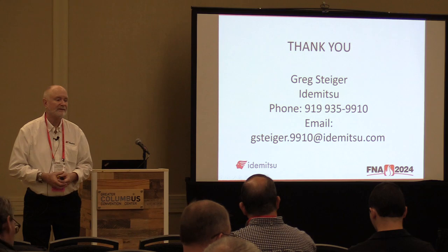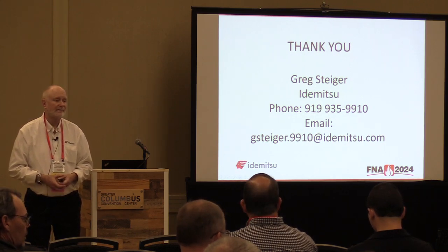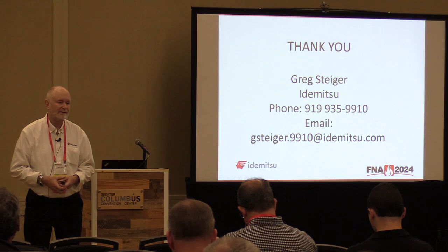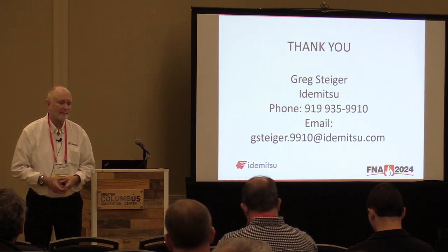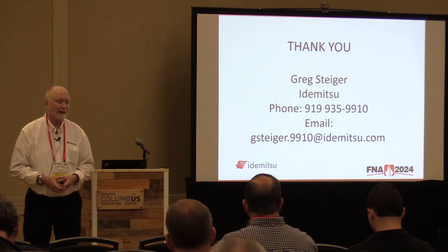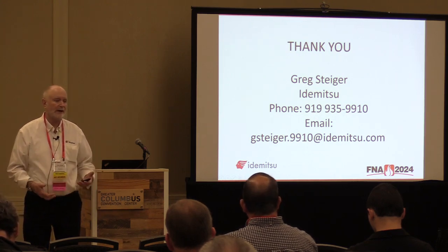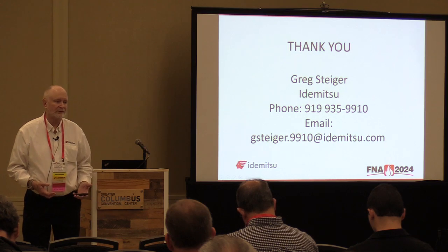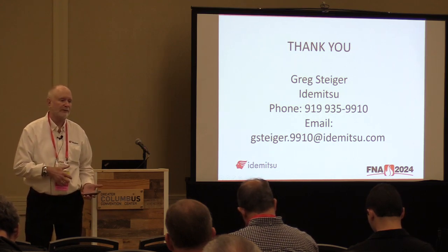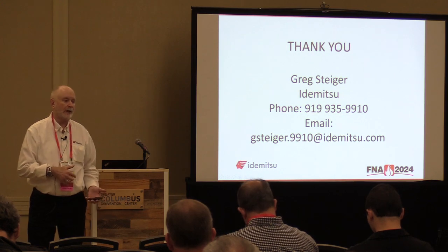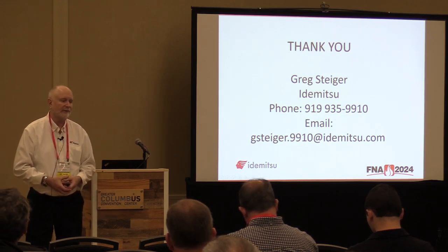Are the production centrifuges normally sized to give you a long centrifuge cycle? Or if you've got a 5,000 gallon tank, are you running it continuously and it's never going to get to that point where it cleans up good? If you're using a portable centrifuge, you're going to need a long centrifuge cycle. But if you're using a vertical centrifuge and you put it on a kidney loop system, you don't need that long of a centrifuge cycle.